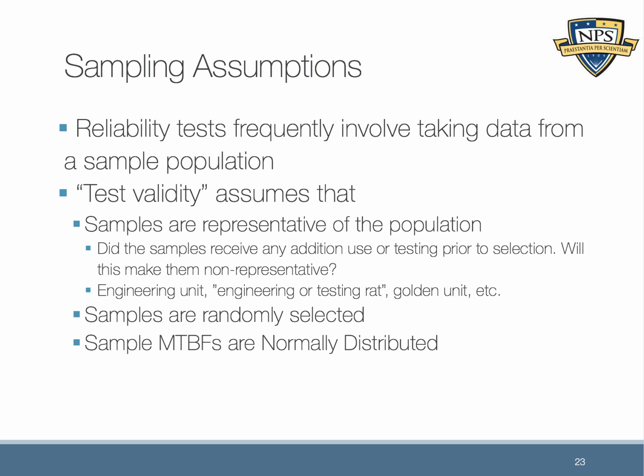You should go to your production line and walk down the line and just pull one off and say this is a randomly selected sample. It shouldn't be based on the way it looks, shouldn't be based on its prior test results. It should just be based on walking down the test line essentially and pulling one off, right?